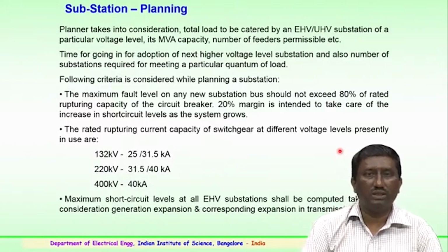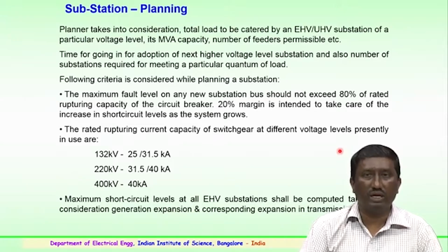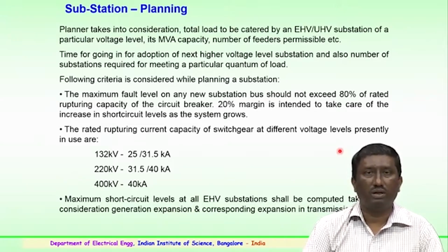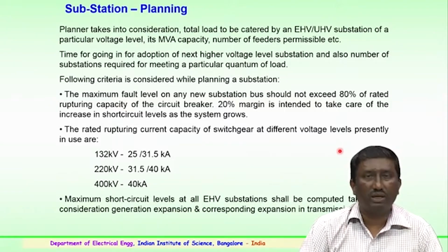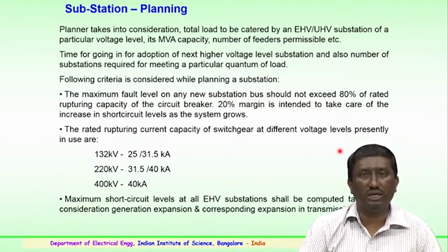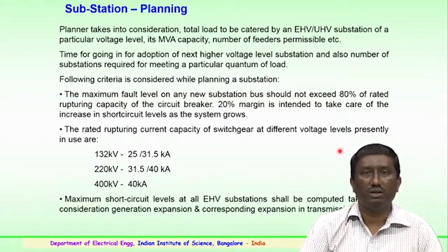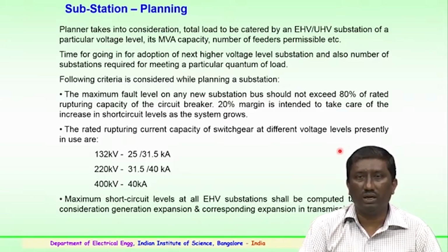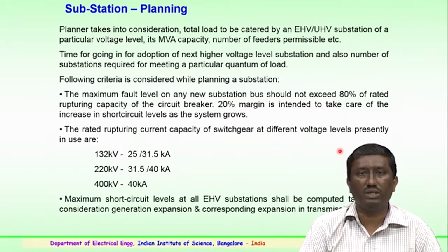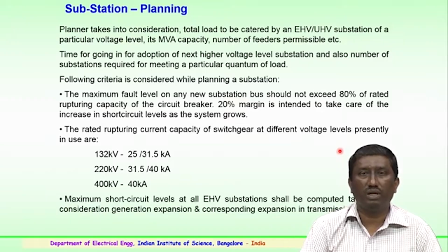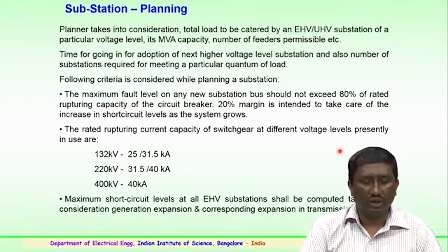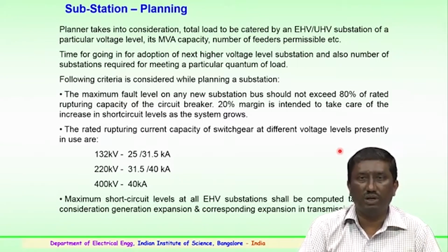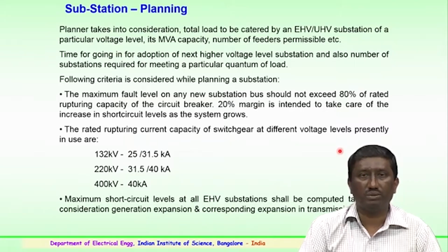So, again, substation planning is a very important task, similar to transmission planning. Here the planning engineers have to take into consideration the total load which is to be catered by an extra high voltage or ultra high voltage substation of a particular voltage level, its operating MVA capacity, and the number of feeders which are permissible in that particular planned substation.